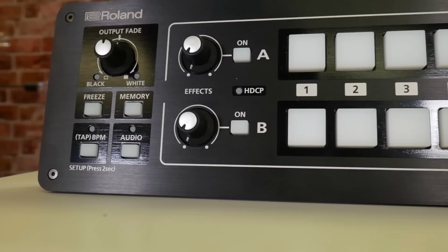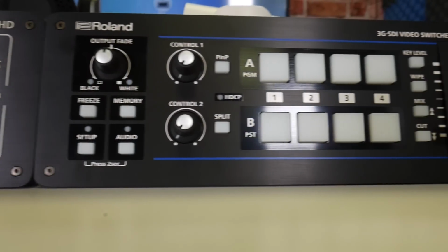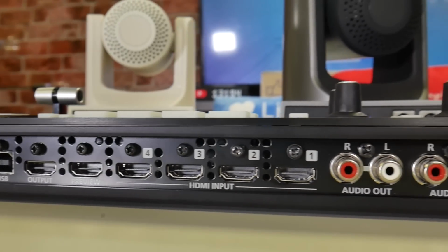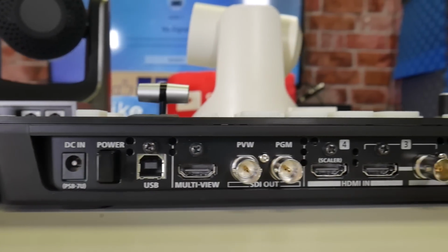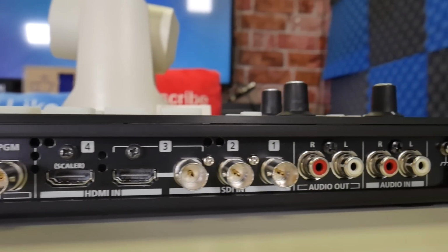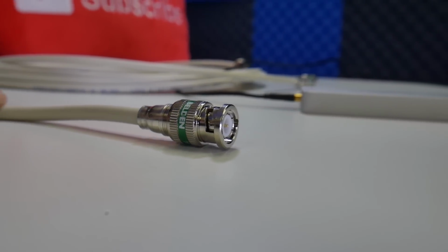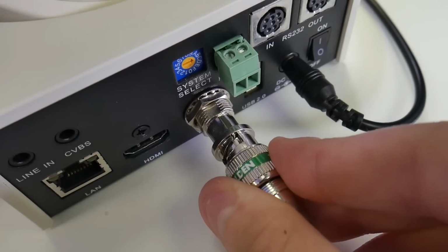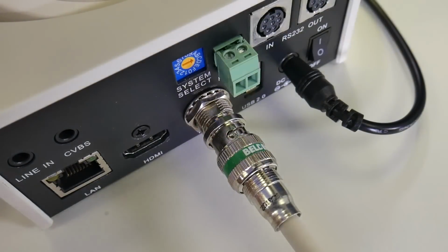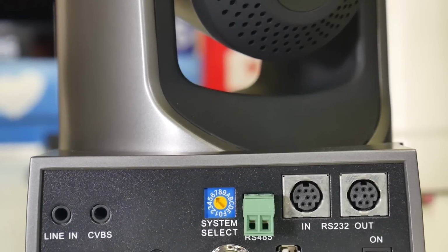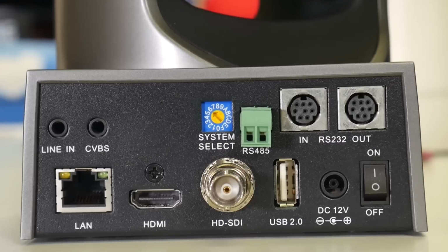The Roland V1 HD is Roland's HDMI switcher. For this switcher, we will plug in all the HDMI inputs from the cameras. If you are using the Roland V1 SDI, you can connect your cameras via HD SDI and still have extra inputs for HDMI to be used for computers and other HDMI devices. SDI cabling is generally used for long cable runs to remote cameras. The locking SDI connectors ensure a secure connection preferred by most professionals. Luckily, PTZOptics 12x, 20x, and 30x SDI camera models all include both HDMI and SDI.